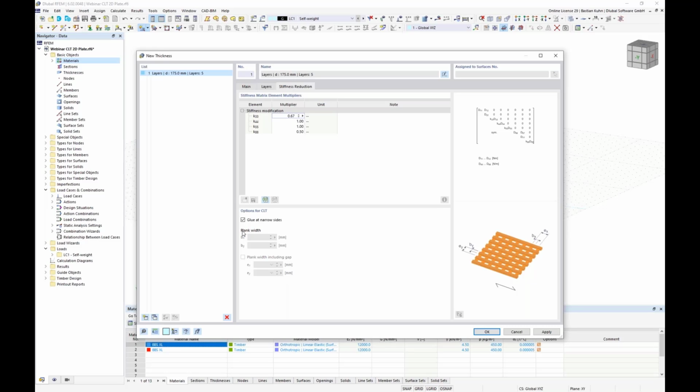They do not assign it for the stiffness, because this is in the values that I just showed you. The EY, you saw it, is still 0 there, but they are using a little bit higher shear strengths. But stiffness, because of cracks in the boards, they are not increasing it or not regarding it.